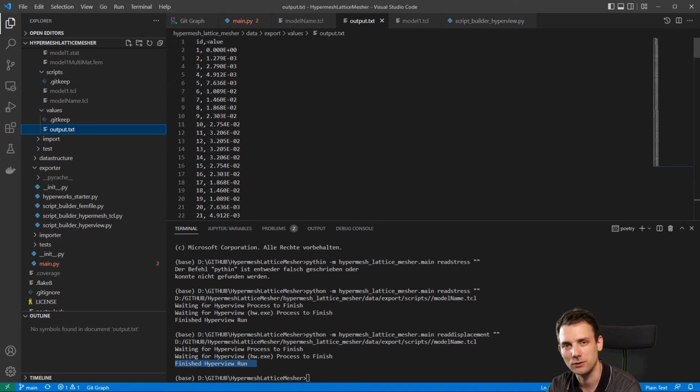You create just a bunch of properties with different diameters, and you write that out as a FEM file. Then you have the sorting method where you can just give a dictionary, for example, where you have each and every element ID and the basket it should belong to, and then every element is put into the right property. I should say the right property is found, assigned to the element, and so on.